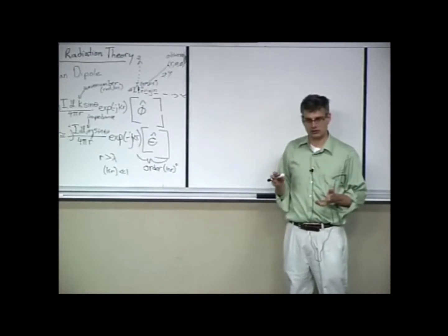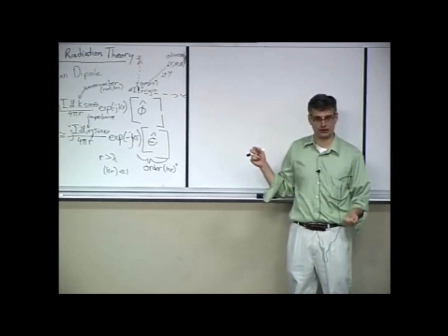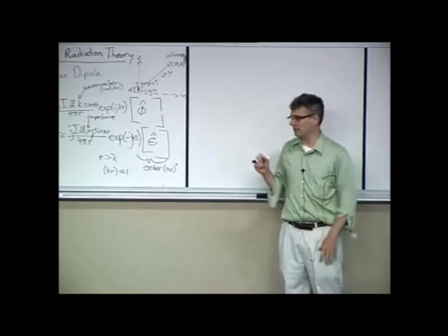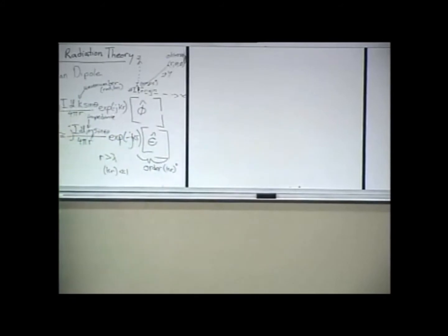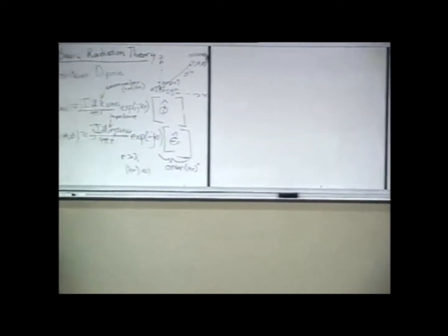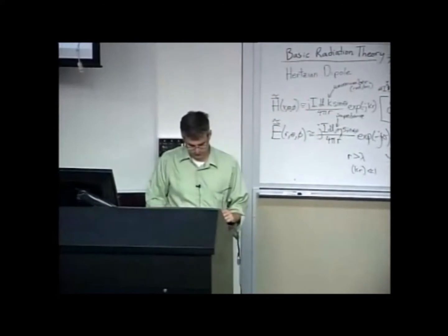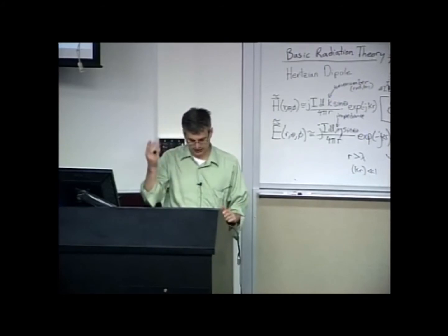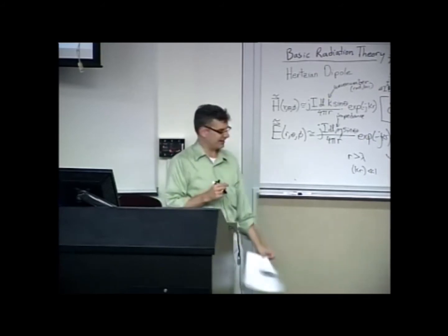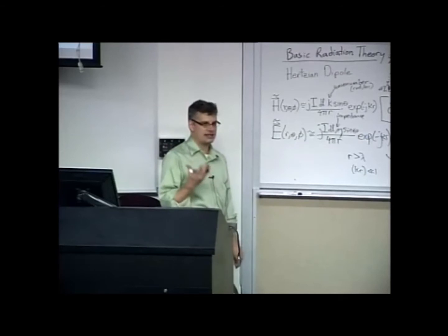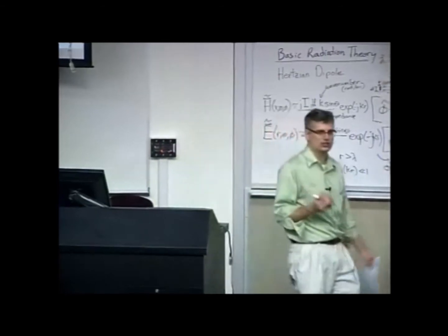So now, because I'm always operating antennas in the far field anyway, I can use that Hertzian dipole to build up more complicated antennas. Before I do that, though, this is a really nice simple antenna that I can use to define the principal characteristics that we're going to use to characterize an antenna.